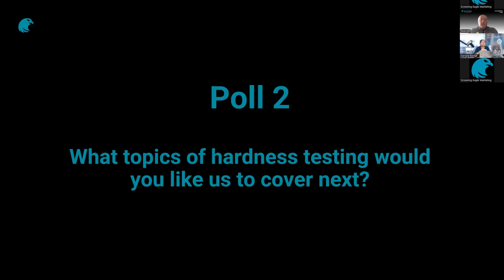Maybe let me read out the second one. How do I know that the roughness is sufficient? Conveniently, we have two ways to do it. That's always a question. Nobody carries a surface roughness profilometer with them in the field. They're rather expensive and fragile pieces of equipment. So we now have to get down to practical ways to tell whether your surface preparation is adequate.